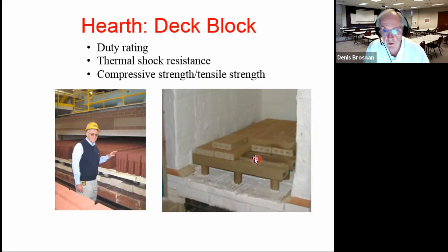So these products are typically cordierite-like compositions, low thermal expansion compositions, trying to minimize any thermal shock damage because they're heated up and cooled quite a lot. In higher temperature kilns, meaning higher than you can expose cordierite to, they may be high alumina products or silicon carbide, something of this nature.